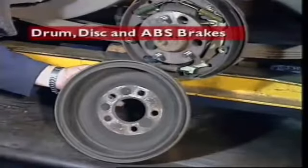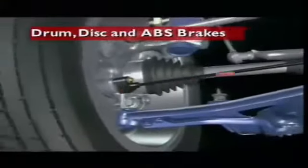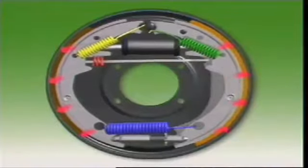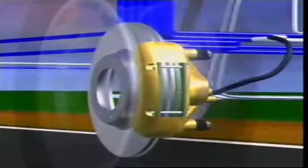This section examines drum, disc and anti-lock brakes. Drum brakes have a drum attached to the wheel hub, and braking occurs by means of brake shoes expanding against the inside of the drum. With disc brakes, a disc attached to the wheel hub is clamped between 2 brake pads. On light vehicles, both of these systems are hydraulically operated.